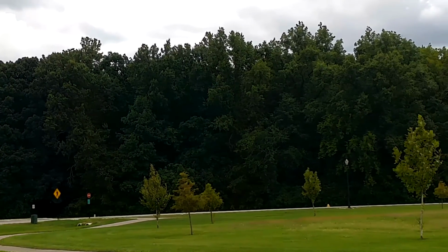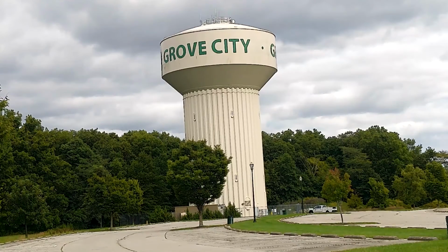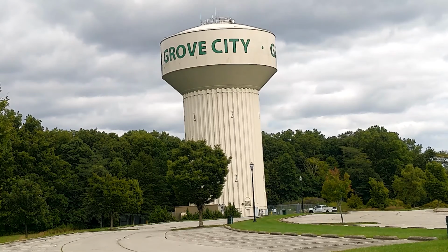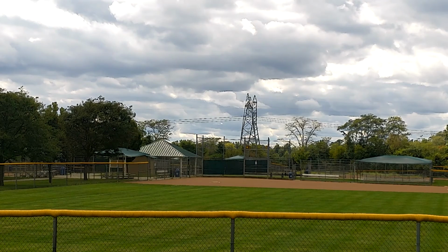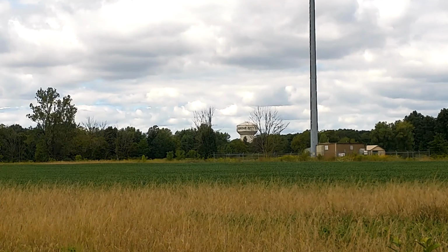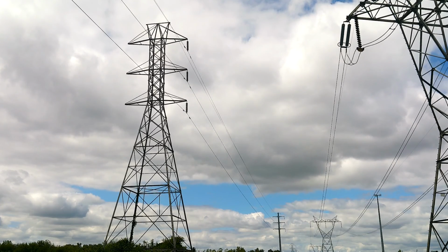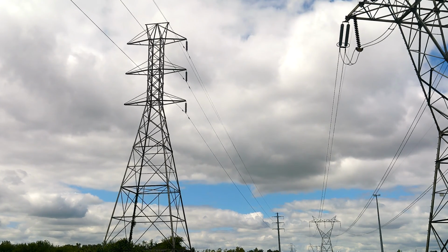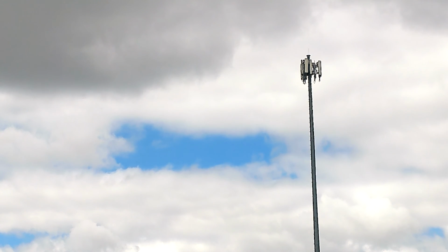We visualized the tree line and determined the trees are approximately 120 feet high. The water tower by the landing area, we've looked up on the internet and it is 189 feet high. We visualized what's beyond the trees and found that there's just open fields. There are 2 high tension lines running through those fields at about 150 feet. And on the southernmost portion, there's a telecommunications tower that is 200 feet high.